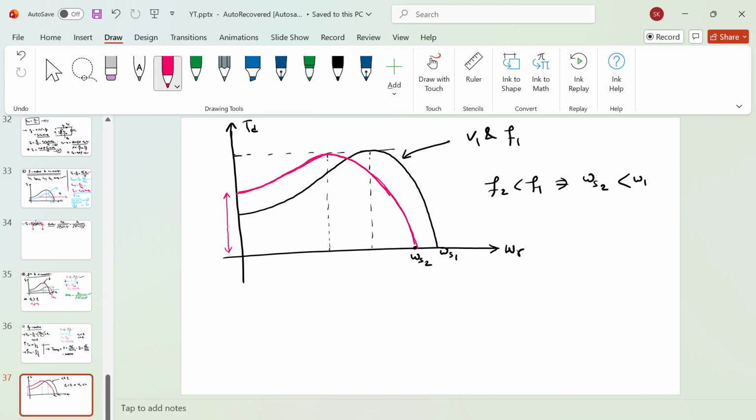And let's say, can you comment on the load or the power factor and all? Let's say you are driving a constant load torque. You have the slip here now, and you have the slip again. You cannot comment from this particular figure, but it has been observed that in case of this V by F ratio constant method, your starting torque will increase, your maximum torque will be the same, and your rotor power factor will be improved this time actually. If you take one example for this particular question, you will get to know your rotor power factor will increase. Although from this particular figure it is not clear, it actually happens in practical life.